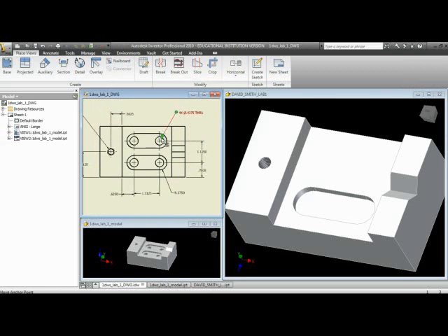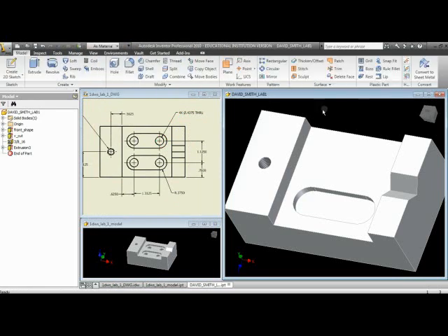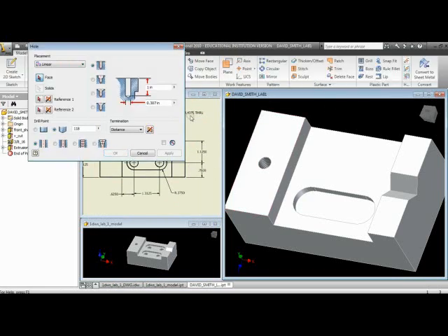Now, at this point, I could just array this up, if you will, and I could have arrayed the original sketch up while I was in the first sketch. But I think it's better to get as much as you can done and then array those at the same time, because I do have these two holes, and these two holes in that slot look exactly like these, so then I can copy all of that.